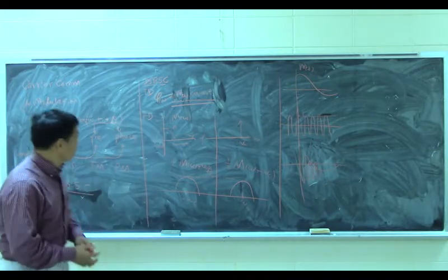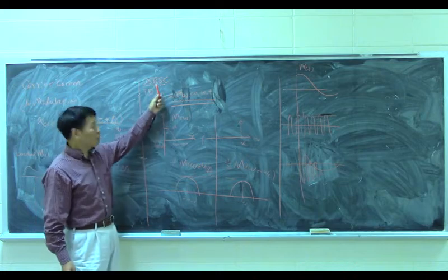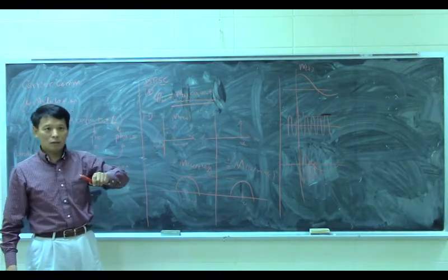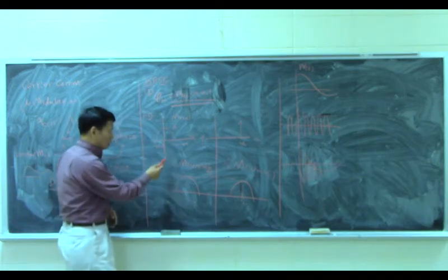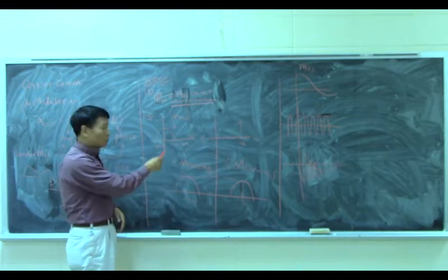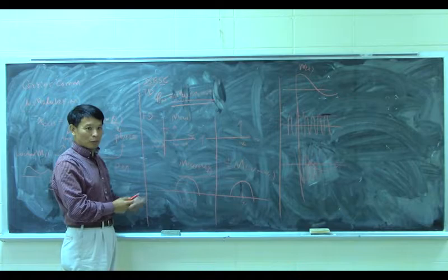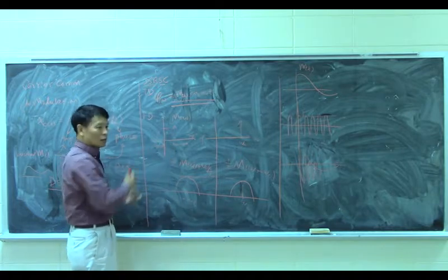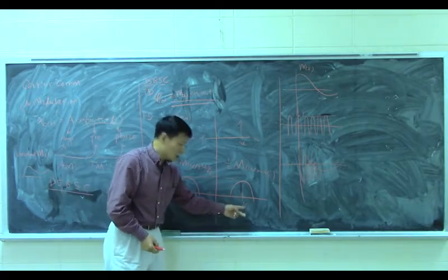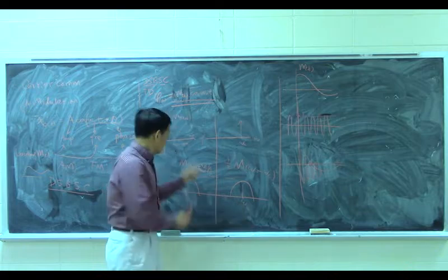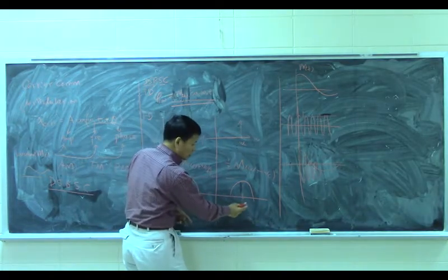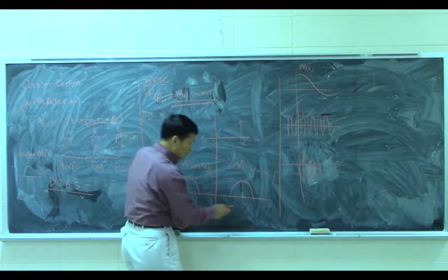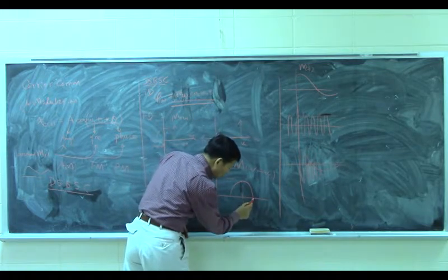Okay, now this is called double sideband. Why do we call this double sideband? Look at this. The bandwidth here equals 20K, from 0 to 20K, but mathematically we have it from negative 20K. Now we shift the whole thing to the right-hand side, centered at omega c. What is the frequency here?